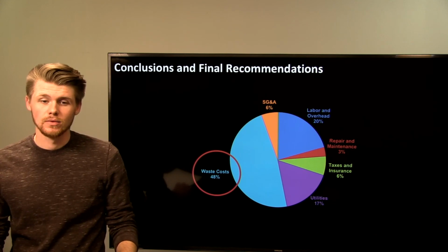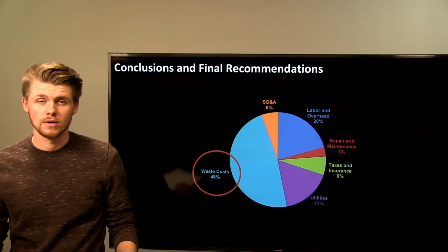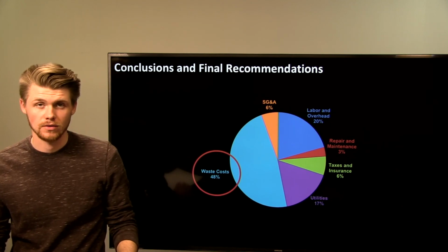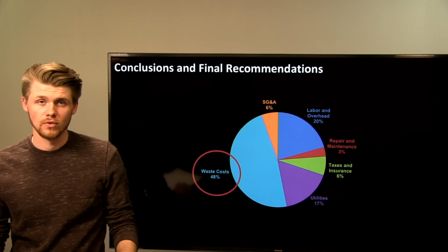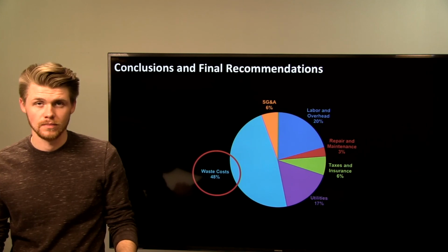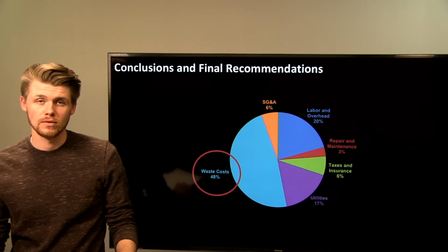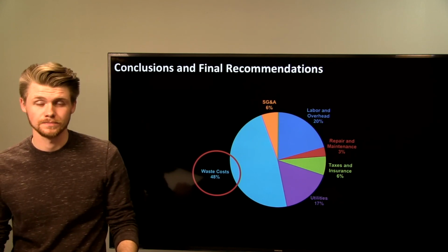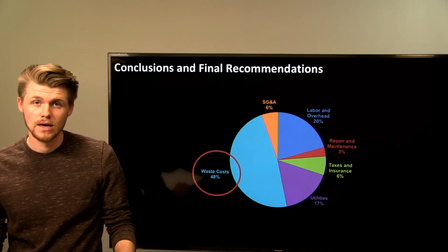So I think what we need to do is maybe decrease the temperature on the reactor, or try to completely remove the methanol before it goes in the reactor, because the methanol conversion to formaldehyde is what creates that in the system. So if you could remove that methanol contaminant, it would also be easier down the road getting out the acetone too. So just to recap, go ahead and build it.